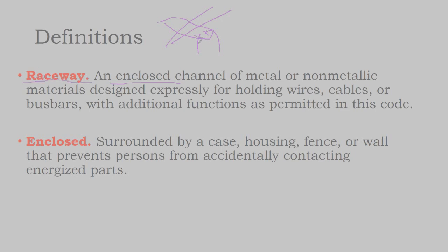And so the question is, if you have these exposed circuit conductors that are not fully enclosed in a metal raceway, then you're just asking for a code violation. If you have DC conductors coming off the back of the module and they're inside the home, they must be in a metal raceway.